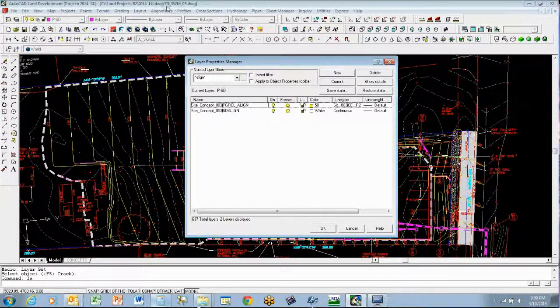We are working in the storm drain stormwater management drawing, so we need to create our own layer that's specific to this particular drawing. Anytime you see this type of layer name with site concept, that's telling us this is an X reference layer, because the site concept plan is actually X referenced into this drawing.